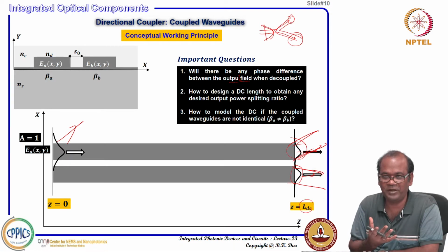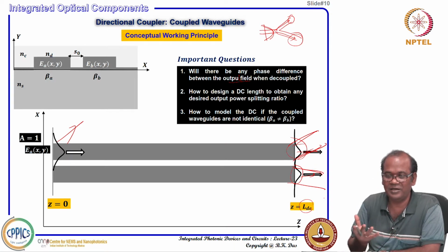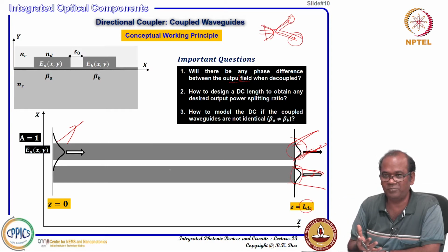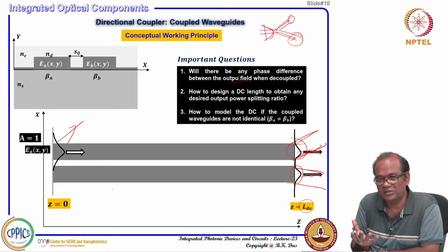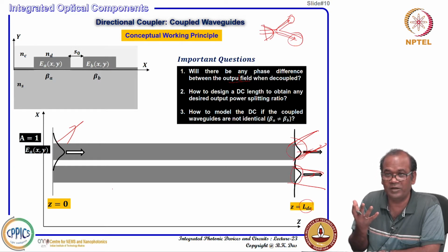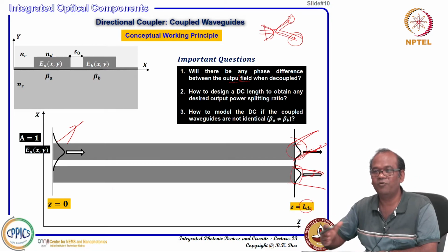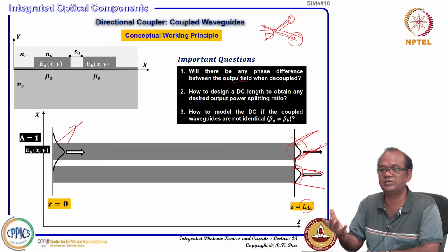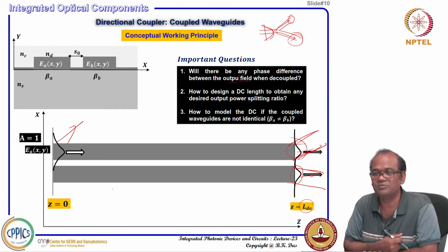That gives us a pretty good understanding that if there is a coupled waveguide, you can really couple light, you can tunnel light. But if you want to use them not just as a splitter, but in photonic integrated circuits, then normally you have to interface another device. Whenever interfacing one device to another, you do not work with the power intensity, rather you work with the amplitude and phase. Because integrated photonic circuits, entire circuits, you can analyze in terms of amplitude, because there is a phase relationship that can cause some kind of interference.